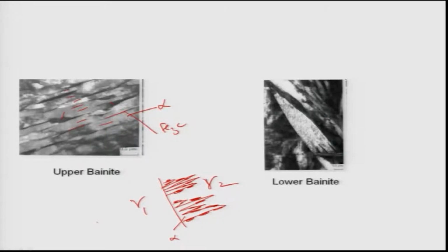So that is what actually happens for the alpha, and this alpha is the same thing as Widmanstatten alpha. They are not like the allotriomorphic alpha, they are actually looking like Widmanstatten alpha plates or alpha needles, whichever way you can call them. Many people say needle or plates. The difference is that morphologically they look similar, but a plate has a third dimension that is quite thick.